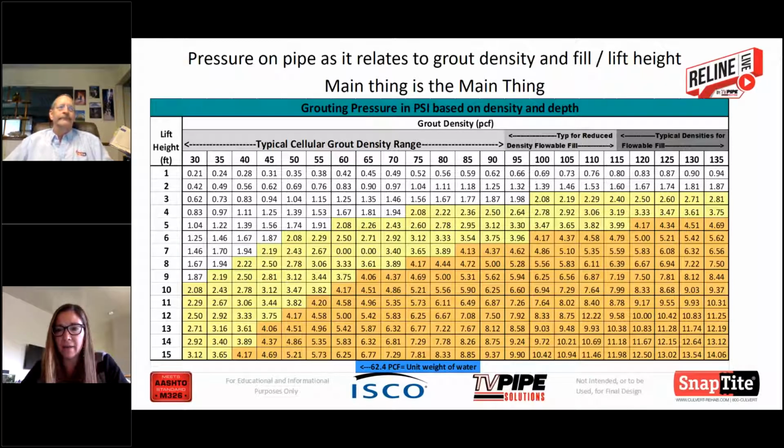HDPE has high expansion and contraction properties. Should a cement-based grout be used for backfilling the annular space between the host pipe and the new carrier pipe, where the pipe emerges from the concrete grout? Total axial bending stresses are set up that may contribute to long-term rupture at that point. Others have recommended the use of a compressible membrane around the pipe, which then allows the pipe to strain naturally and avoids the issue.